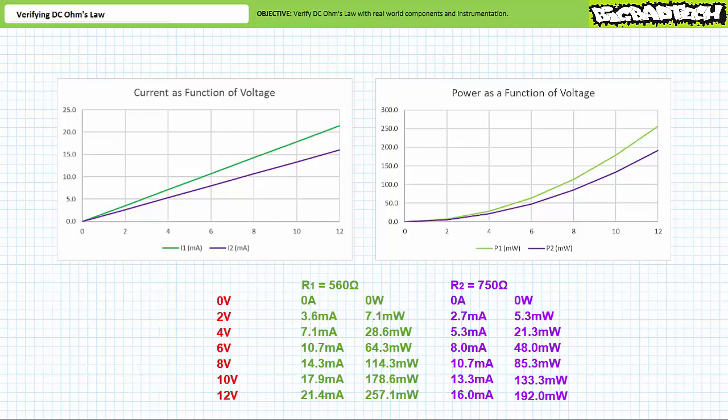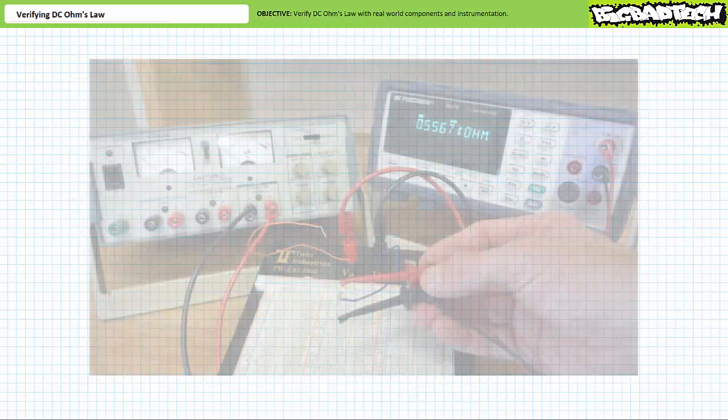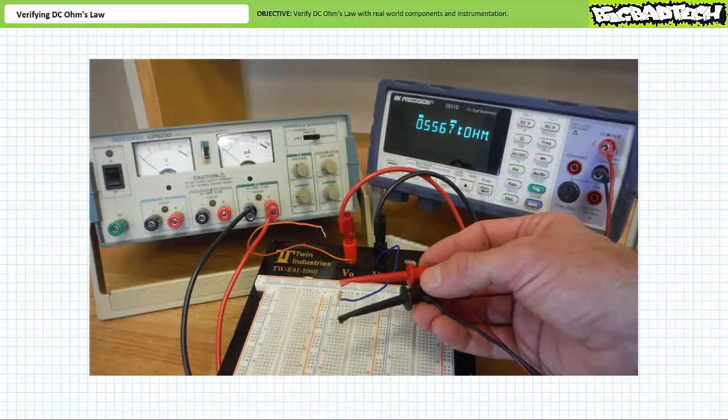I'll walk you through a couple of the first observations step by step. The 4-band resistor color code for a nominal 560 ohm resistor is green, blue, brown, gold, meaning 5, 6, followed by 1, 0. Given a plus or minus 5% tolerance, we might expect this resistor to be between a low of 532 ohms and a high of 588 ohms. An ohmmeter measuring the resistance of a resistor matching this description demonstrates it has a resistance of 556.7 ohms, well inside the expected tolerance range.